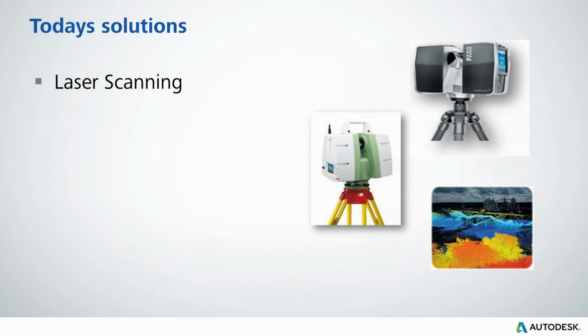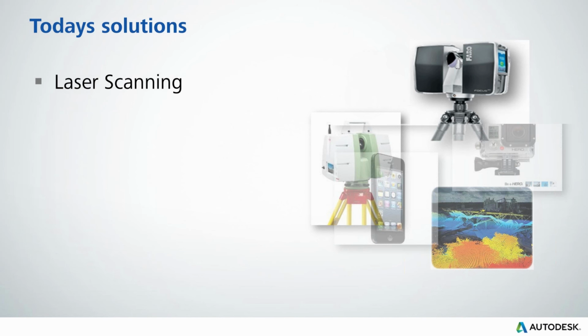There's some drawbacks, however. When you need to set up your laser scanner, of course, that takes some time. You've got to determine exactly where to set that scanner up, and you've got to have line of sight access to the entire pile, which means that if you've got very high piles, being able to shoot the top of that is maybe going to be a challenge. So there are challenges. It's not impossible, but it's definitely something to consider.